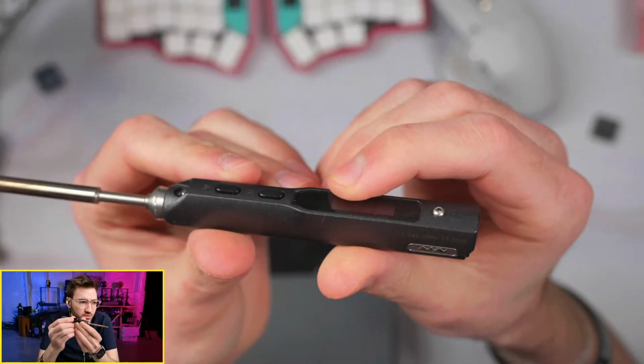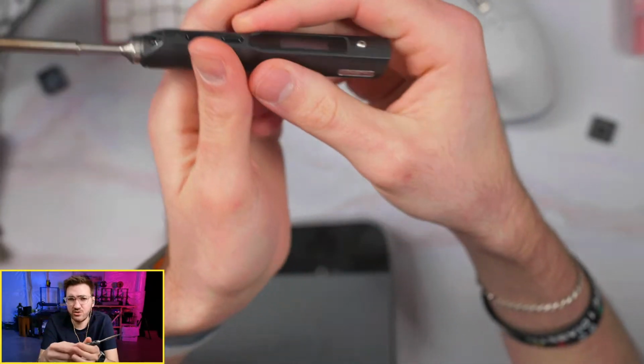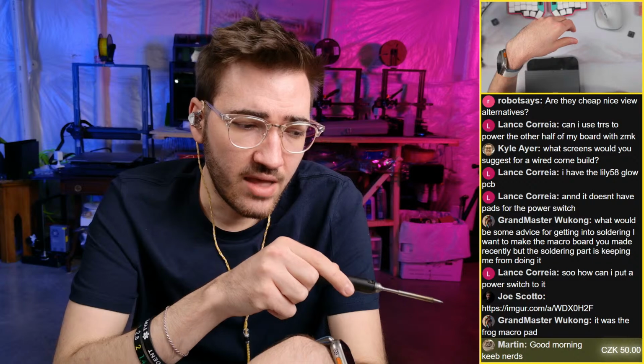It'll just hold the temperature, and it just makes it easier. If you get one of those cheapo ones, it's not going to work as well. So you could cheap out and get a $20, $30 soldering iron, but these are like 60 bucks. They're not that much more. So I'd highly recommend going with a good iron, getting good 6337 solder, and then that's really all you need.